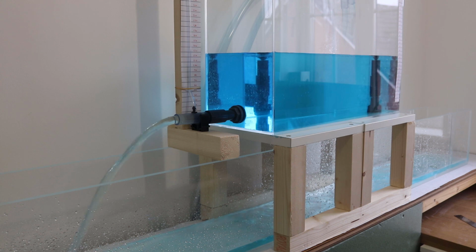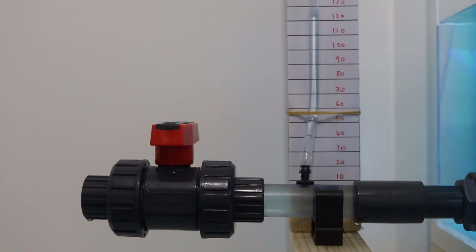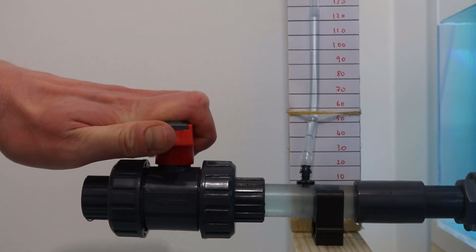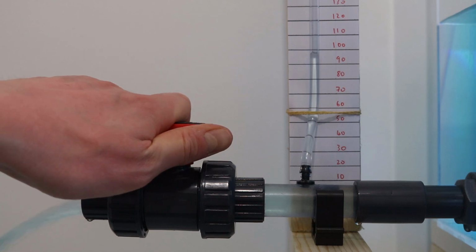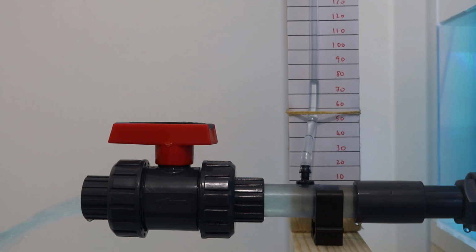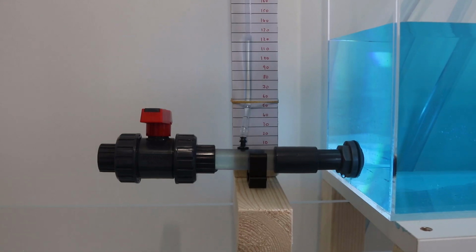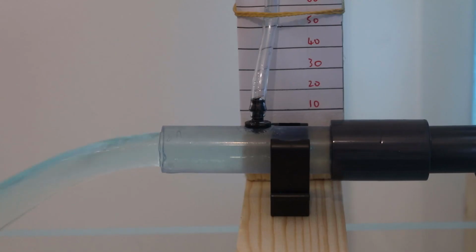But now we have moving water in the system, we need to revisit our total pressure head equation, as we now have another form of energy in the system. As we open the valve on the system, we can clearly see that the pressure in the pipe drops, as energy in the form of pressure is converted into movement or kinetic energy. And if we take the valve off the pipe altogether and let the pipe flow unrestricted, we can see that almost all of the pressure is now converted into kinetic energy.